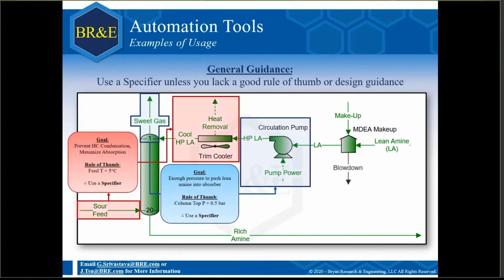What about something less direct? What if I want to prevent hydrocarbon condensation while maximizing absorption? We've covered this a bit during our amine sweetening webinar, where the colder it is, the better it is for absorption. But if you put it too cold, you will start to have hydrocarbon condensation, which is not ideal.